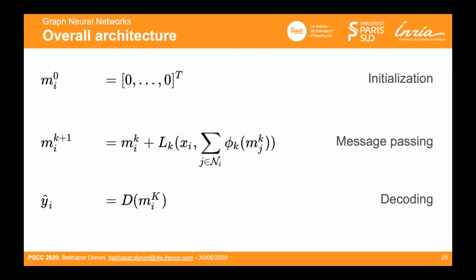That's a good question. In the AC power flow problem, you will encounter a very important problem. You cannot perform an AC power flow on an infinitely large power grid, because the voltage phase angle really needs to take into account the full grid. It's not a very local information. The theta is a global information, so you really need to gather information from all the grid.